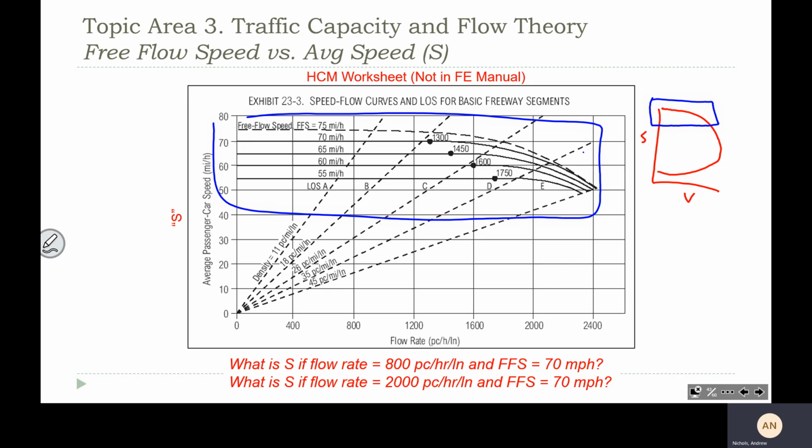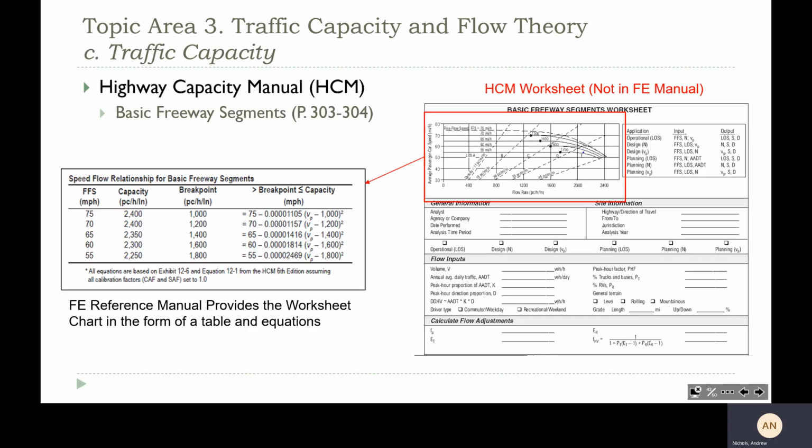And the Greenshields models, I should have mentioned this earlier, are completely theoretical. If you look at real data, it's not like once you go from 1 to 2 vehicles, their speed's really going to be impacted. So it can keep building traffic up to a point, and then that's when it really starts to tail off, which is what's indicated by these breakpoints. So at 70 miles per hour free flow speed, the speed doesn't start to be impacted until you get at least 1,300 vehicles per hour. And then the more you add from there, it starts to drop off more significantly. So that's all that's happening in this table.